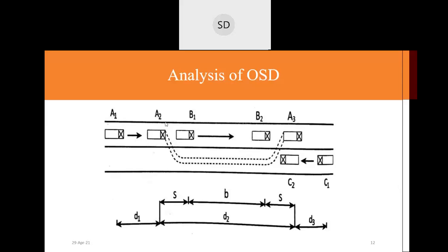Within that reaction time, the fast moving vehicle will reduce its speed, follow with uniform speed behind vehicle B, or maintain a speed equal to vehicle B and follow it with a clear spacing S, and he will look for any opportunity to overtake vehicle B. So that is the concept.